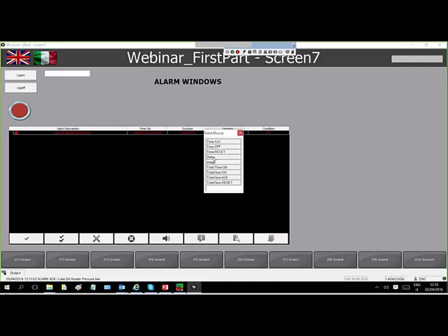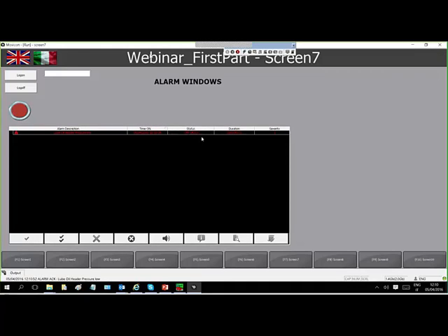I can add the status that says the alarm is off, and acknowledge. Here is the duration, it was on for 1 second. Severity. On the gray line, you can resize, add, remove fields through this field choice line. If you click here on the gray, it will open this field choice line, letting you add or remove fields, normally in development, but also in runtime.